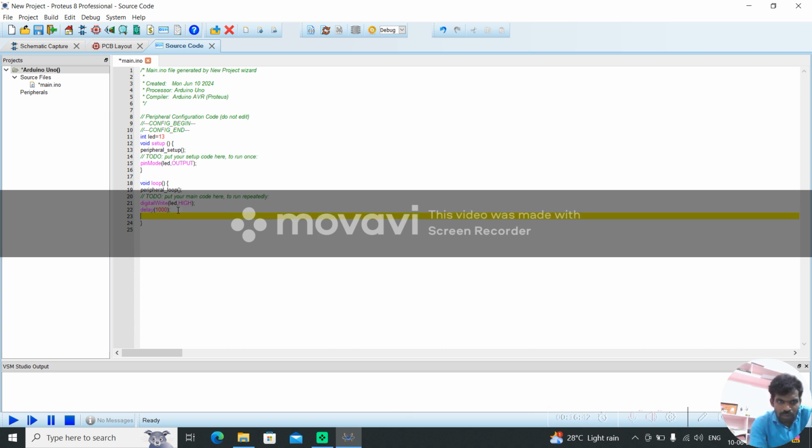Now we are going to write for off. That is digitalWrite of LED comma LOW, and let us add the delay again, the same delay, 1 second, that is 1000 milliseconds.